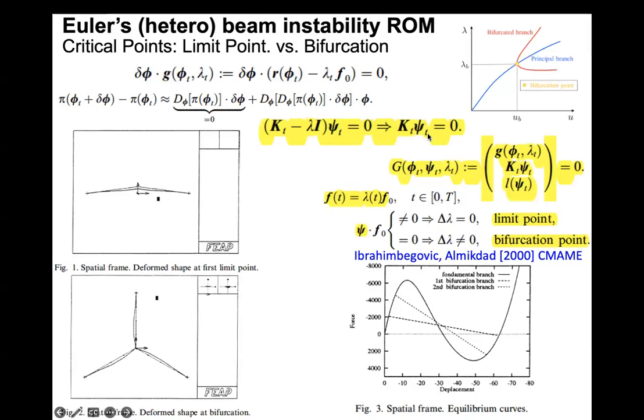And so if you want to obtain exactly the result when you get these critical points, these are the points where a small perturbation load will lead to a very large, disproportional response with large displacement, large rotation, and so on and so forth. You can then make an analysis which shows how to distinguish between a limit point, being the point where you can no longer climb, that's the ultimate resistance of the structure, and something called a bifurcation problem, where typically the structure snaps from one shape to another.